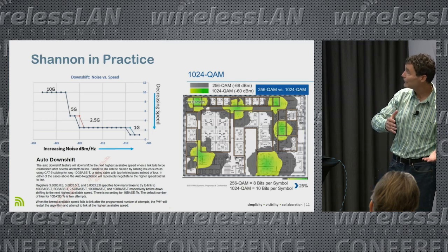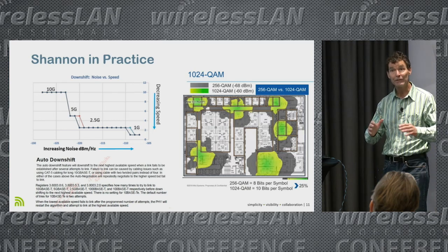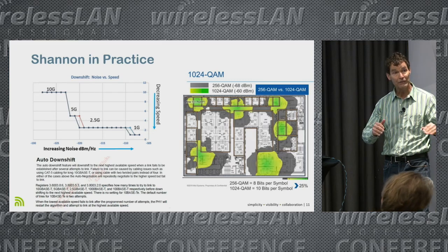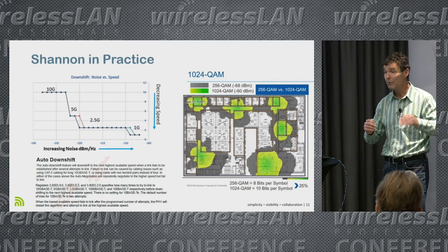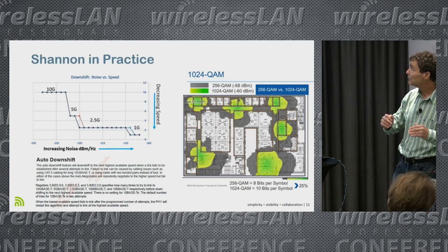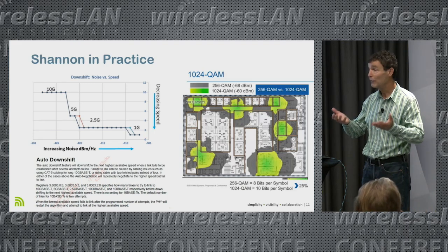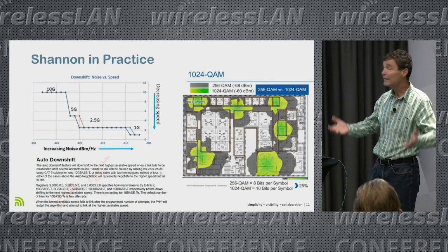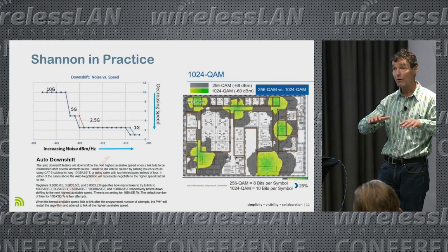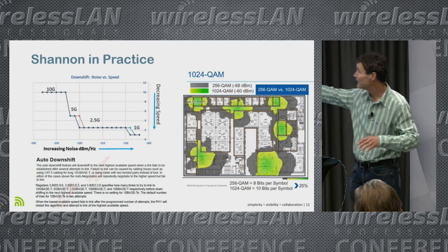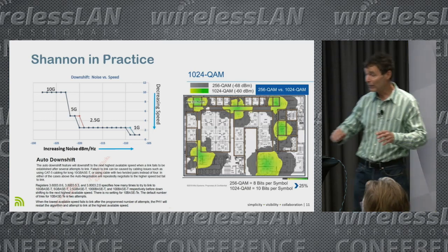Well, it turns out on the wired side, there's something called auto downshift. Most PHYs, as you're beginning to deploy AX and looking to 2.5G, NBase-T, 2.5 gig, maybe even 5 gig link speeds, it's largely going to be that as the noise level goes up on the wire, the speed's going to downshift. And the PHYs actually downshift for you automatically in general. It's programmatic. That's kind of the noisy details at the bottom here, but by and large, that's going to happen.